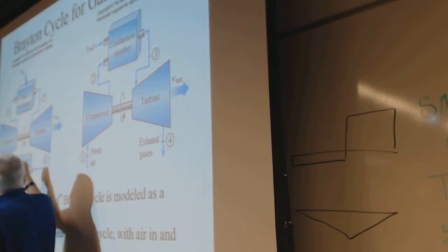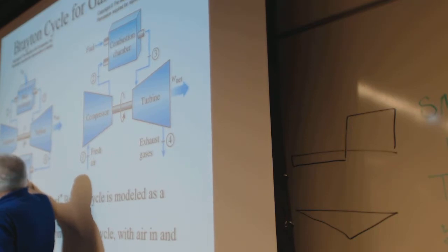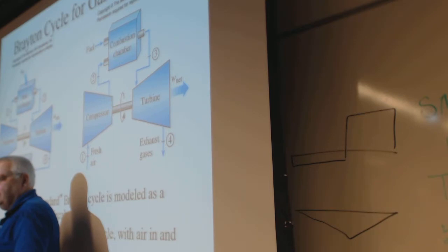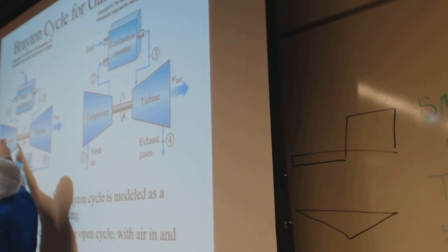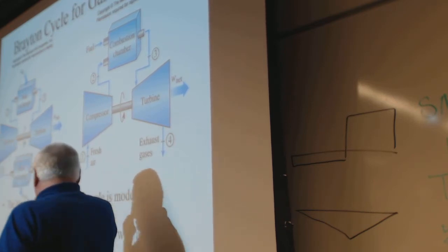When you analyze it, the air comes around and it goes into a heat exchanger. Now it comes out at low pressure and high temperature. And the heat exchanger just magically waits around until it comes down to room temperature, make the heat exchanger big enough, and then around and around it goes at some mass flow rate all through there. That's how we'll analyze it.